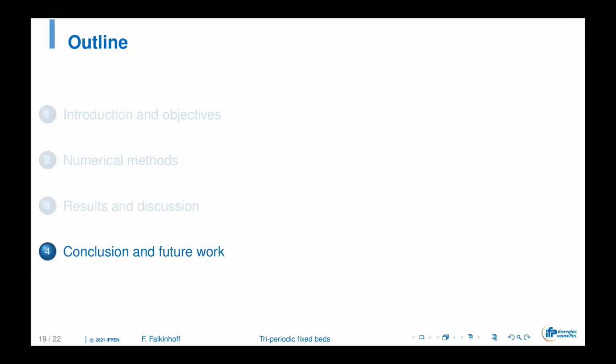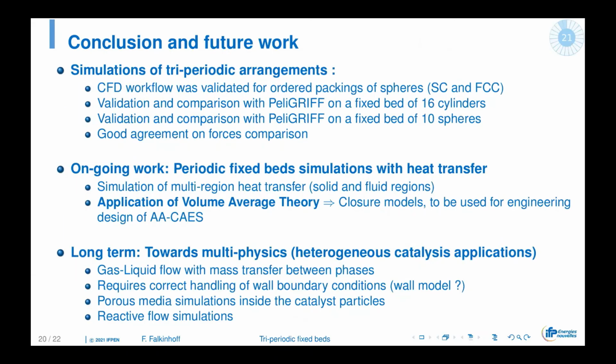Let's go down to the conclusions and future work. I've shown you simulations of three periodic arrangements that were validated on order of packings and also on fixed beds made of cylinders and spheres, and we have a very good agreement on the force comparisons. We will now apply that to more complex beds and more dense beds too, with maybe some issues on meshing in particular. The ongoing work is going to focus on heat transfer.